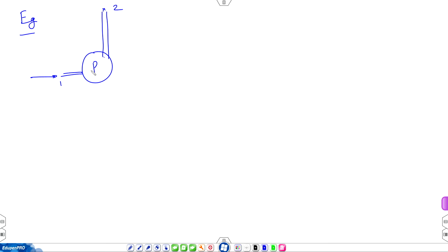So, now the tube is vertical. Here is a caution, do not mix up head difference with the length of the tube. Should the two be equal? Not necessarily, because your tube can go all over the place and then reach the top. So, length can be any, do not assume that length and elevation difference are equal.